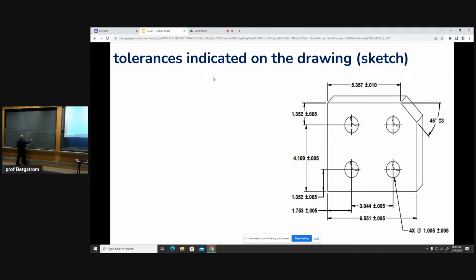And I would have to make sure that these edges were perpendicular to this edge, right? So it would have to be perpendicular, and I guess if they were both perpendicular, they would be parallel, right? And then you can turn it sideways. So if you had a piece of stock that you knew was square, you could make one side the right distance away from the other side. If you didn't know that it was square, I think we've got to stick it up, face it off, flip it over, face it off. Okay, so now we've got two parallel sides.